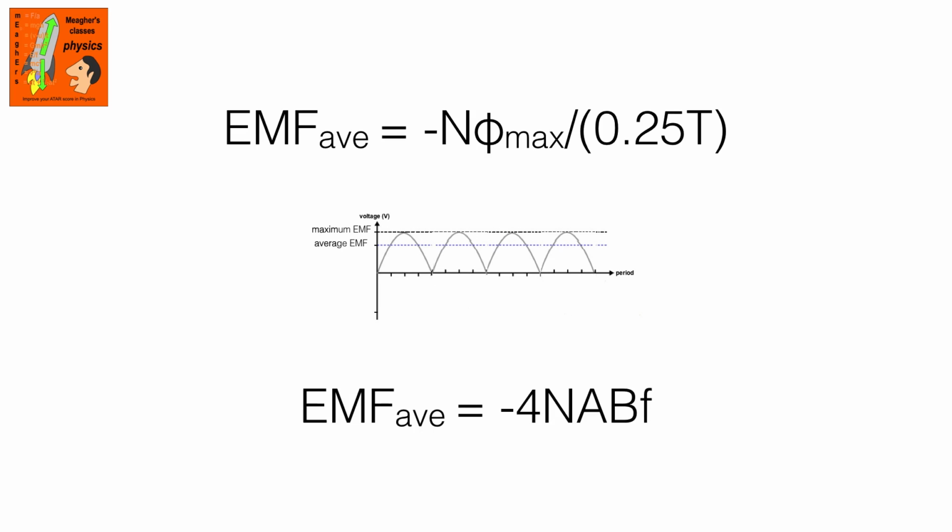I've put in a dotted line to represent this average value and the maximum peak value, which we've shown how we can determine previously. If we look at the area of the curve between those two dotted lines, that red thing there, and for all of the rectified peaks, if we take that area and jam it into the gaps, it fits exactly, if we've got the average EMF in the right location. So with this fully rectified curve, if we average it out over time, there is one value for EMF we can use.